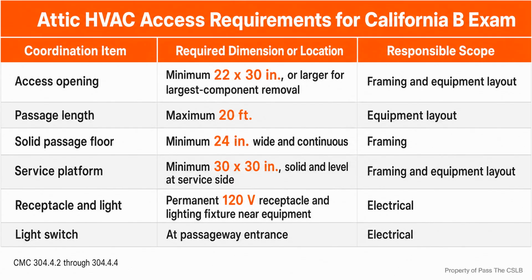The first is assuming that a line flowing on the day of inspection proves the drainage system is complete. Flow today does not replace minimum slope, required size, a serviceable cleanout, or proper termination. The second is assuming that a secondary pan can share any convenient drain route. The source-backed requirement is a separate drain line that discharges at a readily observed point. Hiding the outlet removes the warning function that makes the secondary route useful.